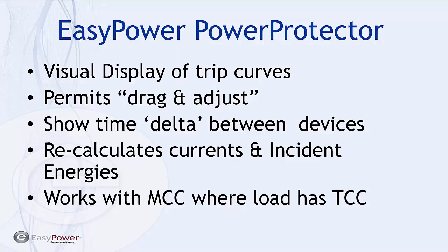One of the features that people like, especially because it's not available in any other tool on the market, is that EasyPower recalculates incident energy and arcing currents as we make adjustments both upstream and downstream, and so you can see at the time whether you're going to end up with the result that you were hoping for or not. And again, this works anywhere, even including an MCC, as long as we've designated the load to have a TCC display.